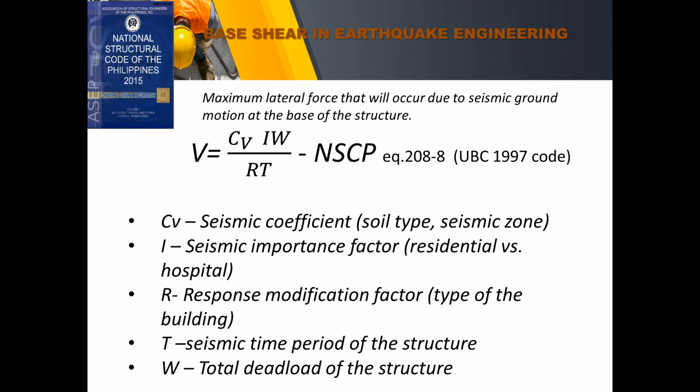We have the seismic coefficient, depending on the soil type and the seismic zone. Of course, we'll refer to the zone map. And then the seismic importance factor. So the importance factor will be different for various occupancies like residential, hospital, garages, and the like. We also have the response modification factor. So it depends on your framing system.